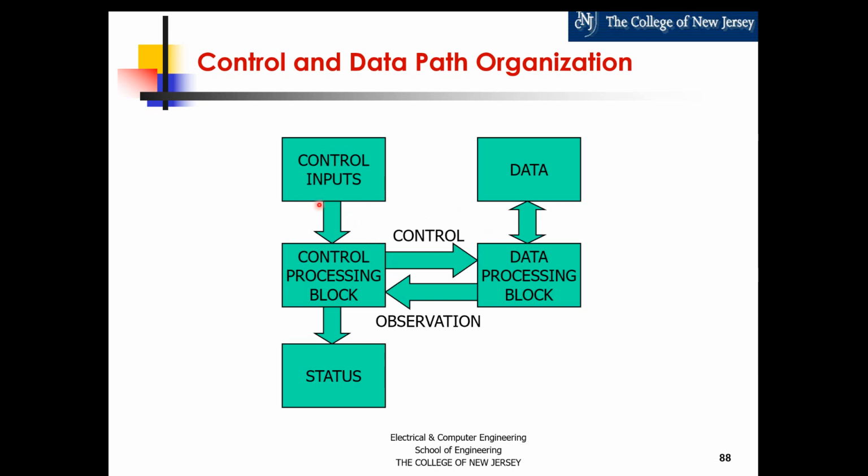So while you are getting these control inputs, you could be at the same time communicating with the data or accessing the data. So that's what's called a hybrid memory organization versus an organization where you will share the same bus between program and memory, but that would cause a bottleneck because you can only access data or program at a time. That's called a von Neumann organization of the memory. So you can see how this could describe a processor.